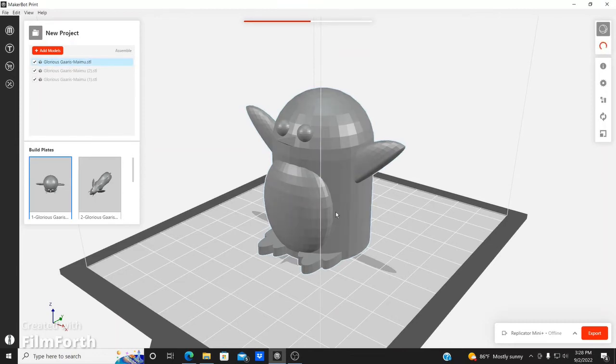It'll generate the geometry, how much filament is being used, what filament material is being used, the time, and also what the toolpath would look like. So it does take a long time as well. And it varies depending on what type of parts you print. If you print a cube, it'll load up right away, quickly. But if you have a complex geometry, it might be in between. It depends on how you change your settings, which will affect your part.